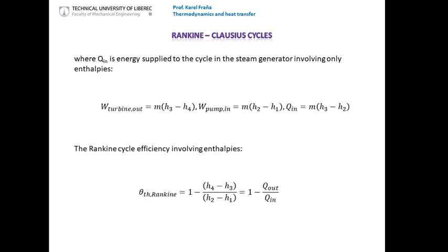That means we can now say that the technical work must be zero, because the furnace and the heat exchanger inside of the furnace, which are responsible for producing the steam, cannot deliver any work. That means the technical work will be zero, and from the first law of thermodynamics, the second form, we know the amount of the heat supplied to the steam is used only to change its properties. That means it can be expressed as the difference of the enthalpy multiplied by the amount of the steam mass.